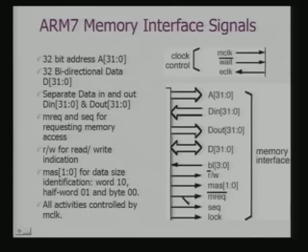This actually indicates whether your ARM core is requesting memory access or sequential memory access. At this point we shall see how to use this signal for efficient access when we are interfacing with external memory. Read and write are for read-write indication. This one we will look at, the size.